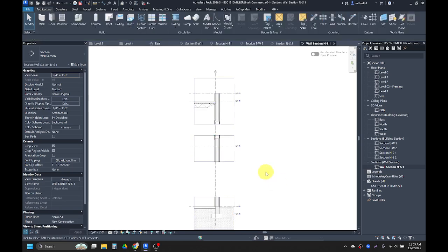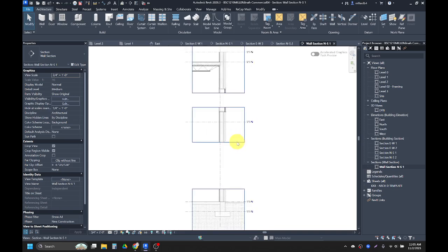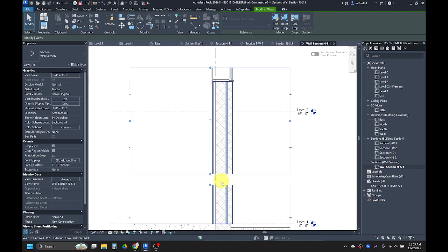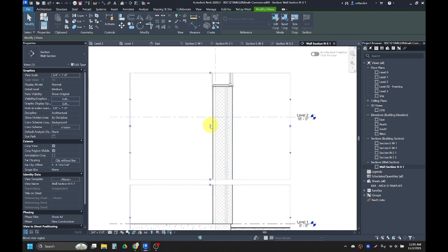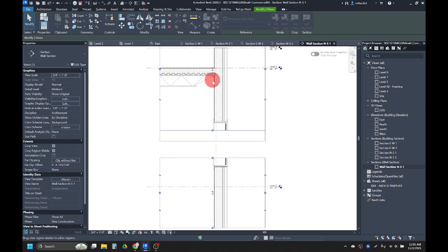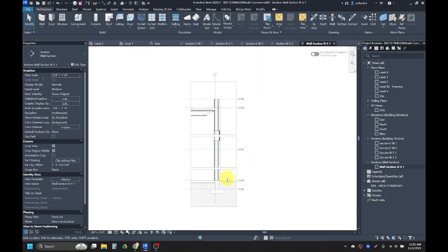And then I'll move that up. I'm just kind of eyeballing the view sizes for now. And then I'll click on them once and I'm going to drag all of it down. I don't want to bring it too close, otherwise it will rejoin, but I do want to bring them fairly close. And this one as well, I'll drag down. So that way I have it as 3 separate views.